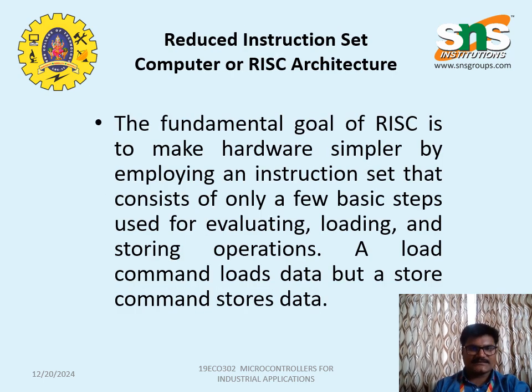The goal of RISC architecture is to simplify the hardware by employing a limited set of basic instructions. Each instruction typically corresponds to a simple operation like loading, storing, or evaluating data. For instance, in RISC, a load command fetches the data from memory, while a store command writes data back to the memory. This simplicity makes the RISC processor efficient and fast.